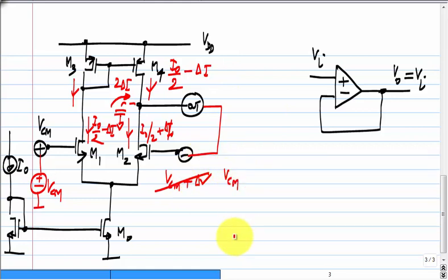Now, even if the transistors are mismatched a little bit, let us say M2 has a slightly higher threshold than M1, because of this feedback action, this will go to something slightly higher than VCM, so that the currents are still balanced. This is the same as when we had drain feedback and so on. In a CMOS inverter, we can't bias like this. This voltage will either rise up or fall down, but when we have this connected like that, it will get biased. Okay, is this fine?